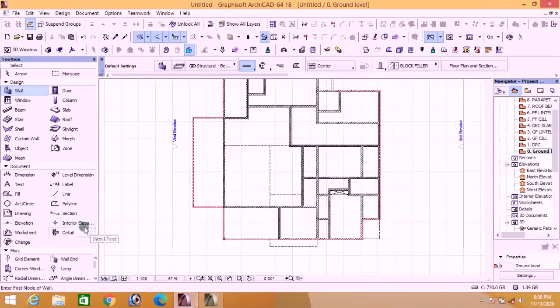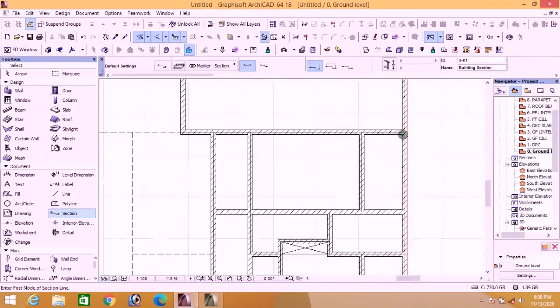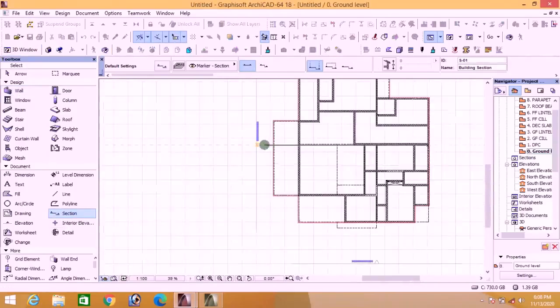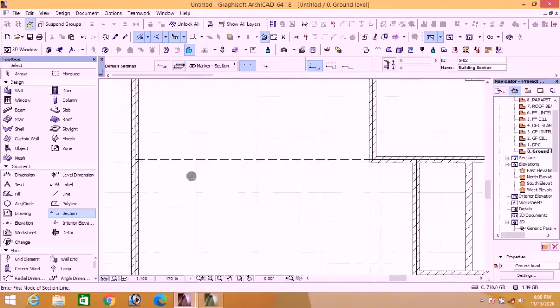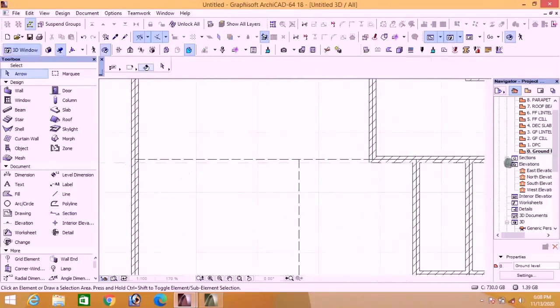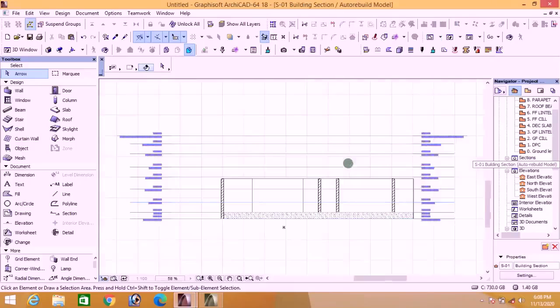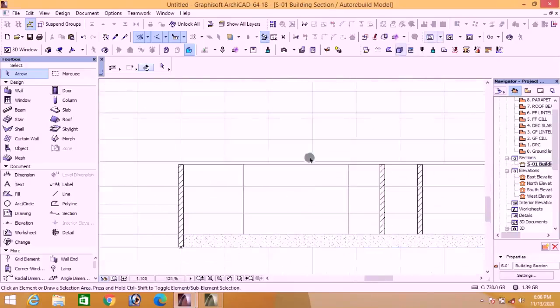In this floor plan, get your line of section. Draw your section from this spot out here and facing towards the side. We want to see what this wall and this wall look like, and introduce our section. We open our section, and you can see what our section looks like. From this spot to this spot is where we are going to introduce our beam.